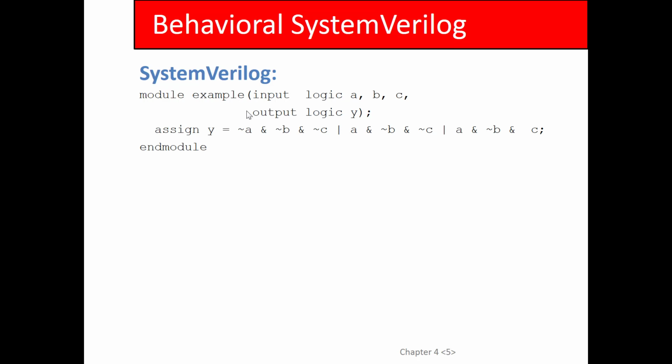And then you have end module here. Notice too that there are no curly braces here. They use the MATLAB or bash sort of style where you have an explicit end to a basic block, as opposed to just using curly braces for all your blocks. So you have module and end module. The other thing I want to point out that I always thought was strange is you put a semicolon after this but not that, which I don't get.